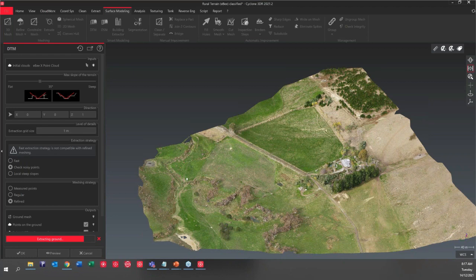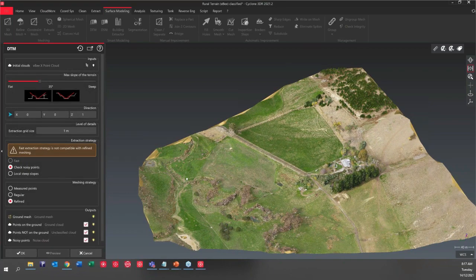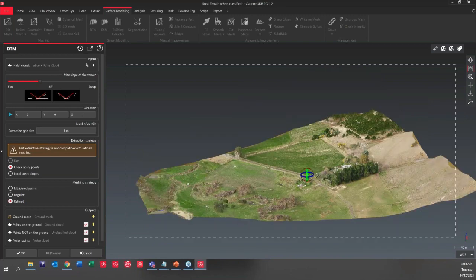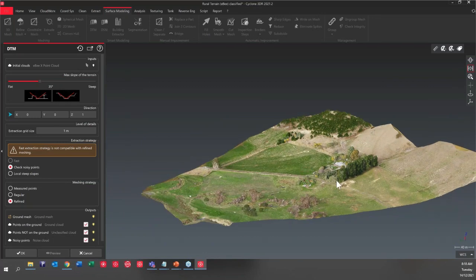When you're refining with the point cloud, so when you're not doing the interpolation, you definitely need to take that into account. You cannot go lower than the quality of your point cloud. But when you're doing the cloud interpolation, you could enter a value that's much smaller because you will have finer details, because it is modeled in the background and it will find the best points to use, basically. Yeah, right. So it'll smooth out any noise in the data, essentially. Exactly. So computation is done, so I think I'll keep going.